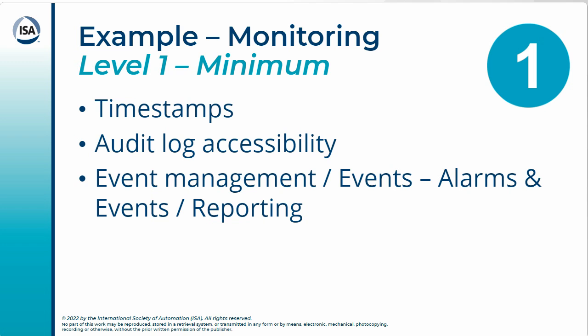So this could be sort of geared towards the lowest level devices. So thinking Purdue model, maybe your 0 and 1 devices, at this point you have to have some way to identify a time for that device, and you have to have some way to collect some sort of logs in that device. And whether you're plugging into that device via serial or Ethernet or some sort of bus architecture, that device has to be able to at least have this minimum set of requirements if you want to use it as part of a monitoring infrastructure for cybersecurity.